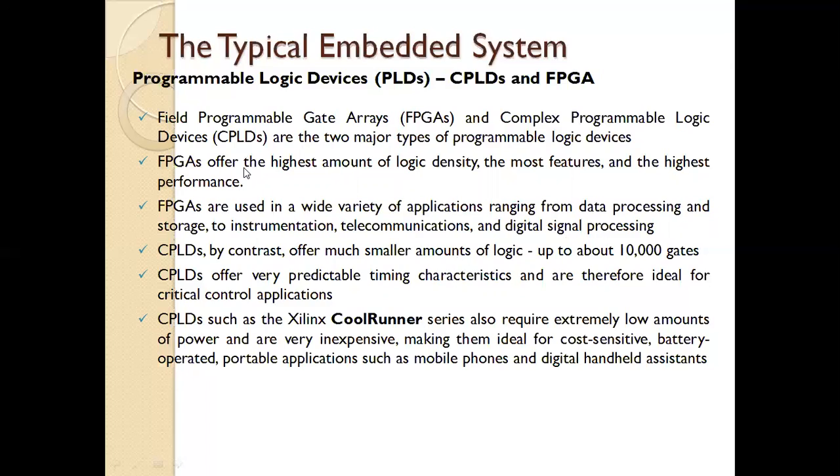FPGAs offer the highest amount of logic density, the most features and highest performance, whereas CPLDs offer very predictable timing characteristics and are therefore ideal for critical control applications. CPLDs by contrast have much smaller amounts of logic gates, up to 10,000 gates. Examples of CPLDs include Xilinx CoolRunner, which are very inexpensive, making them ideal for cost-sensitive, battery-operated portable applications such as mobile phones and digital handheld assistants.